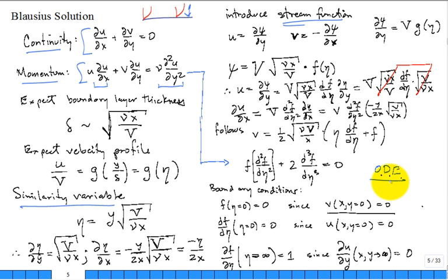Do you remember why in controls they really love to teach Laplace transforms? Why? They take a differential equation, they convert it into an algebraic problem. You play with your little coefficient s, little quadratic or polynomial equations, and then poof, you get the solution. You look to a table, and there's the table of the inverse. And poof, there's my solution. What they did was they took a complicated problem, made it an algebraic problem, simpler, and then back to the differential solution. Well, this is what you do with similarity variables. You have typically PDEs. You convert it to an ODE.